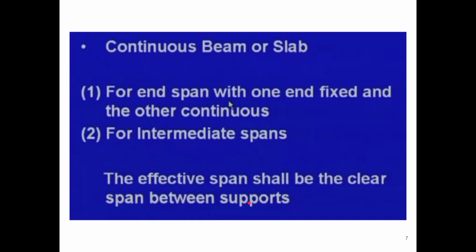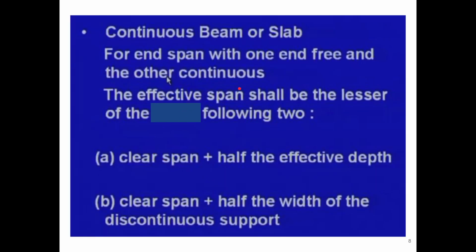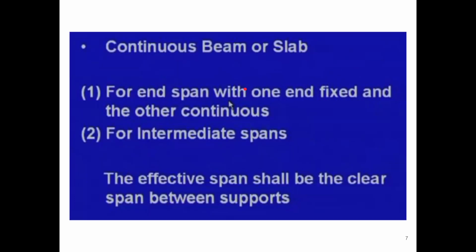In both the cases the effective span shall be the clear span between the supports. Okay, so in this case it is the clear span. It is not plus half width or depth, it is not required, only the clear span between supports. Similarly for the end span, that is the general case, because generally the end span is fixed, but that may not always be the case.